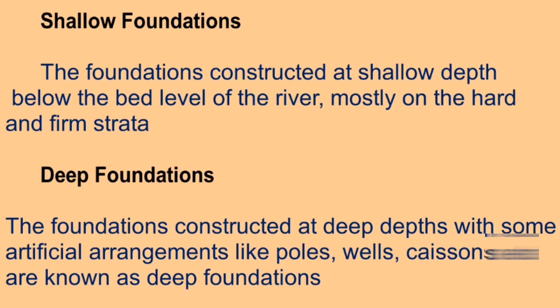And what is a shallow foundation? The foundations constructed at shallow depths below the bed level of a river, mostly on the hard and firm strata, are known as shallow foundations. And what is a deep foundation? The foundations constructed at deep depth with some artificial arrangements like piles, wells, caissons, etc. are known as deep foundation. All underwater foundations in addition to pile foundations are the common examples of deep foundations.